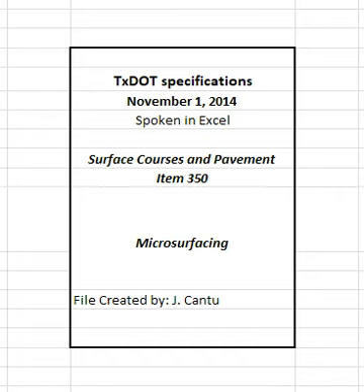4. Construction. Produce, transport, and place microsurfacing as specified in this item or as shown on the plans. Provide emulsion and aggregate that are compatible so that the mixing process will completely and uniformly coat the aggregate.